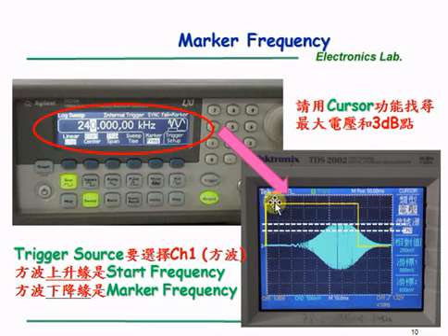The marker function will output another square signal through the sync that will change its value when the signal in the main has reached the desired frequency. For example, if we set the marker frequency to 240 kHz, then using the previous configuration, we could see the output result in the oscilloscope as this, where the yellow line here marks the location of 240 kHz.